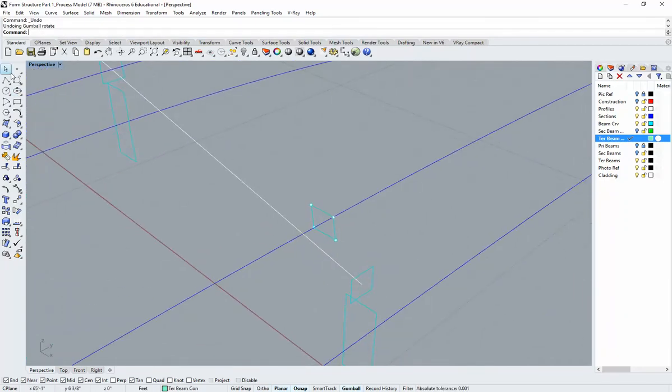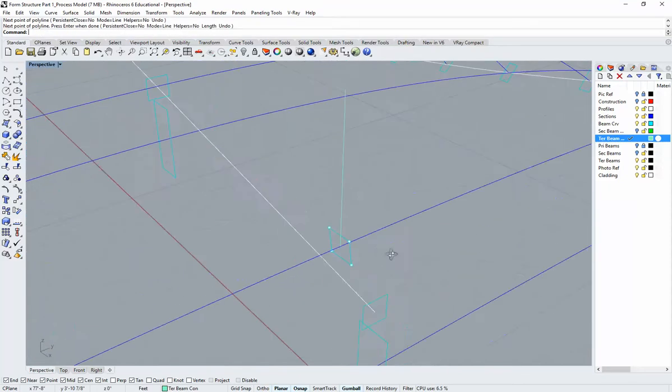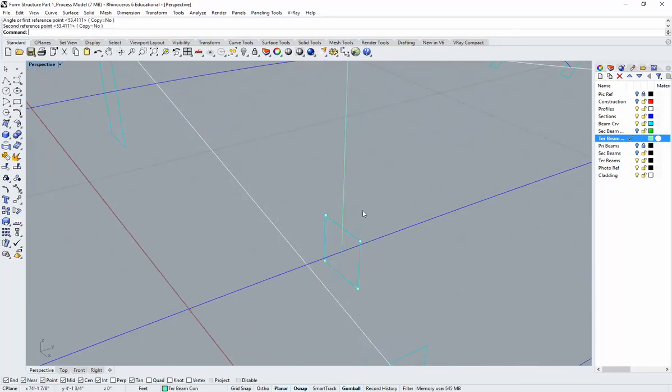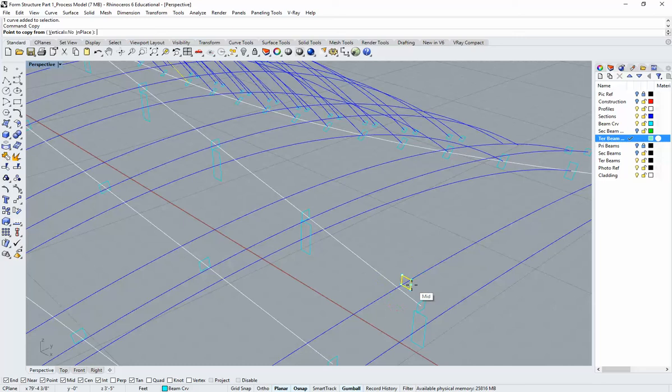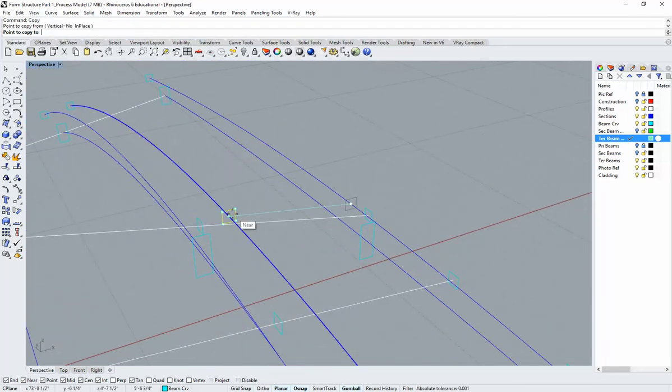We're going to have to just run that line. Actually, never mind. Just draw a simple line up like this in the front view or the side view from that midpoint, and straight up and down, and then do your rotate 3D like you did before here. There we go. Cool. So then you can copy and paste this thing at all the midpoints of the blue top blue section lines.